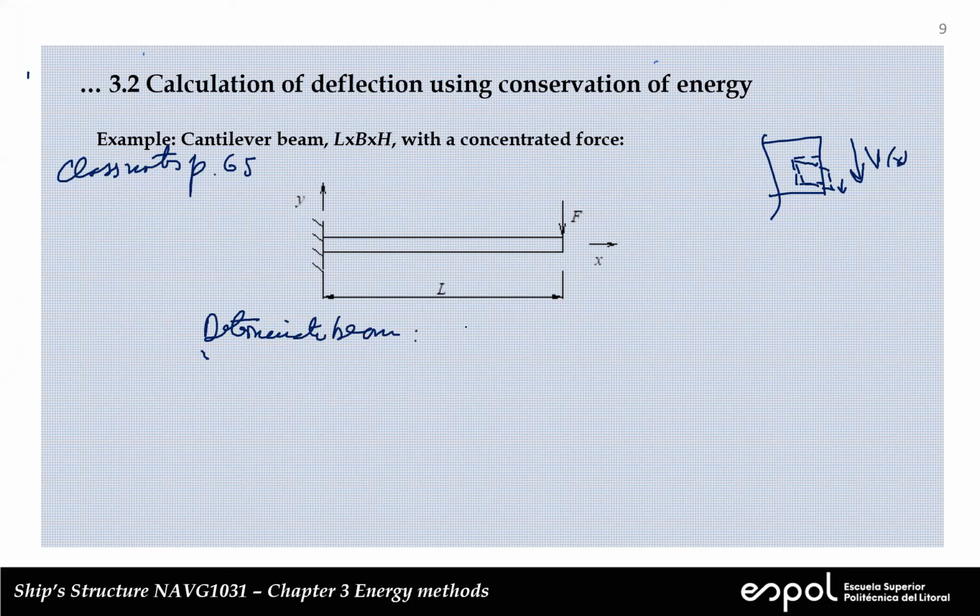So you have two reactions, the reaction and the moment here, because this is clamped. And of course, you have two equations, the forces in Y and the moment in Z. So that's fine, which means that we can apply the differential equation for equilibrium. Would you please remind me what's the differential equation for equilibrium?